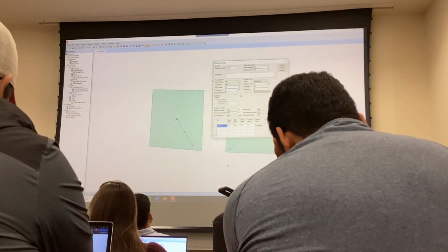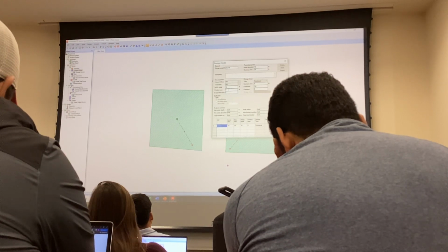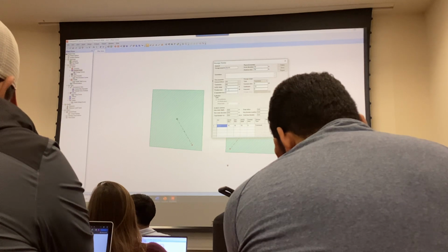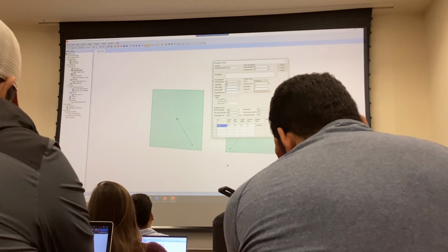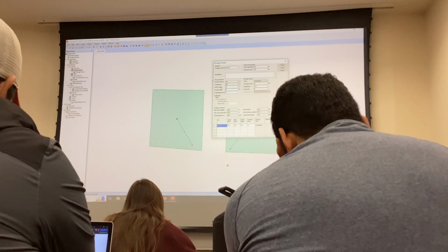Would the water surface elevation be different from the inlet elevation if you had a pond area? When would this be different from just the minimum level? This is your initial. Let's say my detention basin is not a dry detention, just like what you have in front of the civil building, you always see water, right? So your water elevation is not the minimum, it's not the inlet elevation. It has to start somewhere.